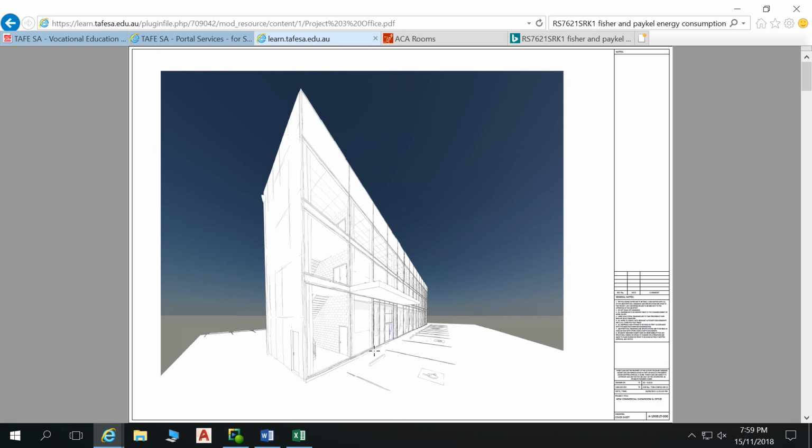But having said that, you can still make fire separation walls from timber studs. You can still retrofit a timber stud wall to make it a fire separation wall as well. So look, I don't know what's behind this plasterboard here, but I could strip it off and find out, and I could probably go to the CSR Red Book. I can't guarantee it, but once I determine what that substrate is, what that framing system is, I go, okay, this is the framing system we have in the Red Book, for example, and that's just one of the design guides.